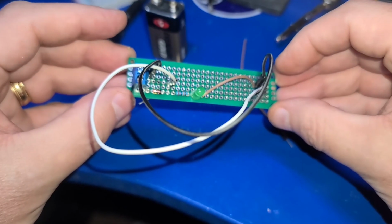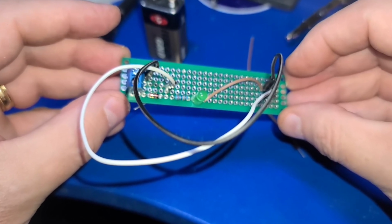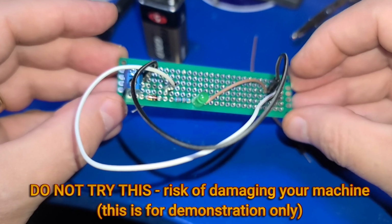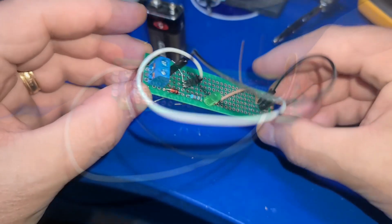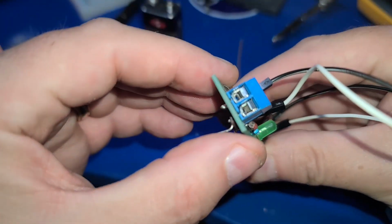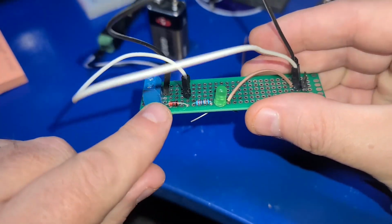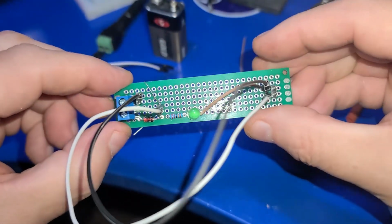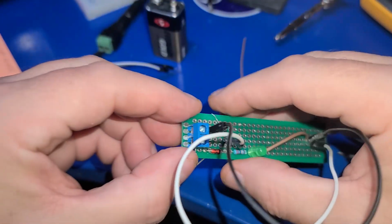The first step in automating the latency measurements is to build a simple board that allows immediate detection when the flipper button is pressed. If you try something like this yourself, you're doing so at your own risk. Here we have a screw terminal, a resistor, a diode, and an LED connected to 2 pins that will connect to the GPIO pins on the Raspberry Pi 5.